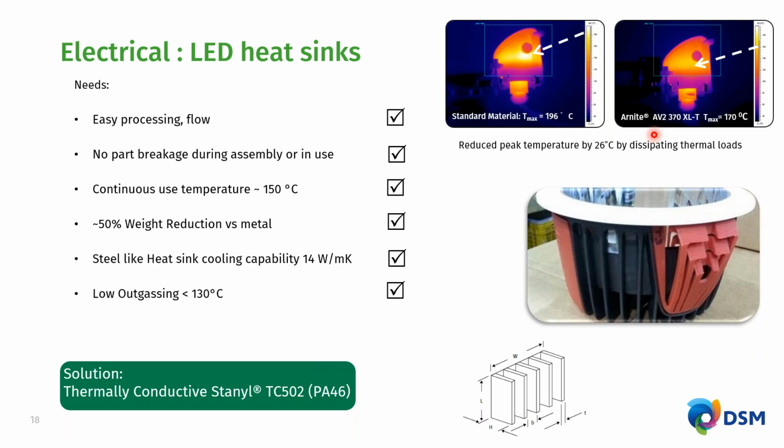And another point I would like to make here is that in applications like this, there are a lot of fins, and these fins have to be also designed in a proper way. So like the distance between the fins, the thickness of the fins, and the number of fins that you provide on the part. And DSM here has very good, in-depth knowledge about how to simulate this, so we can support the customers in doing the simulations and helping the design of the product with our materials.